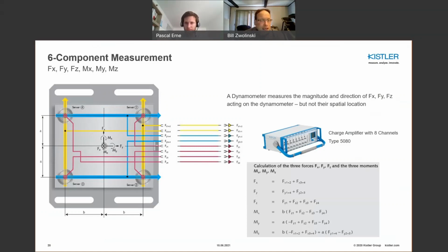What happens in these dynamometers is actually 12 signals. There are four 3-component sensors, but we can pre-sum X and Y together. So you take 4 signals and convert them to 2 total. What you see here on the right is a closed-form expression for forces and moments, which can be computed in software, certainly by your own program, or by the hardware I show you there.